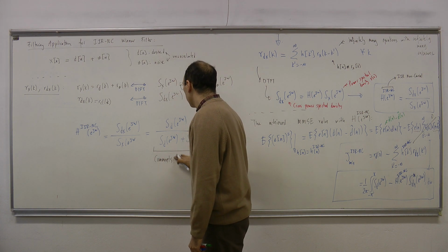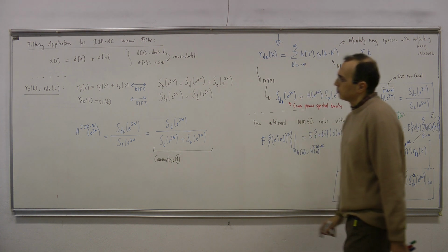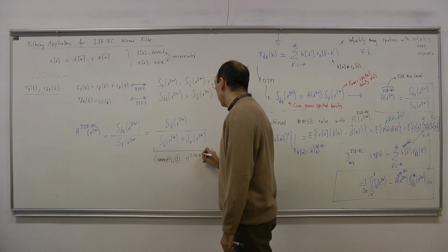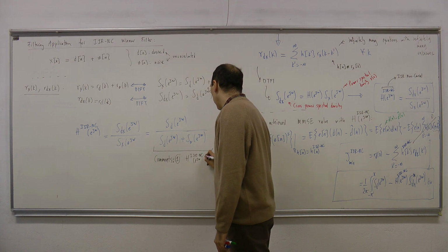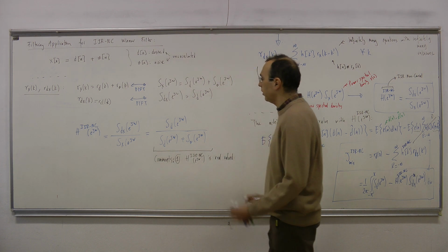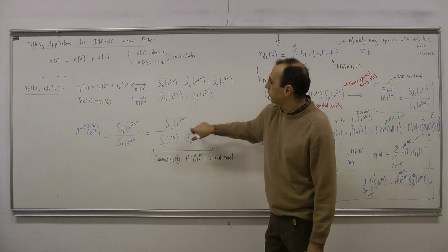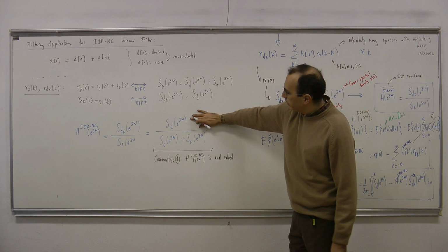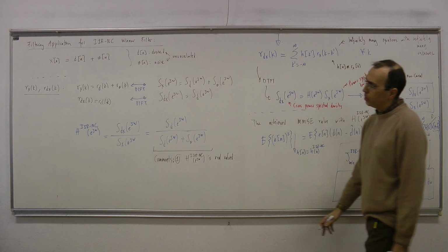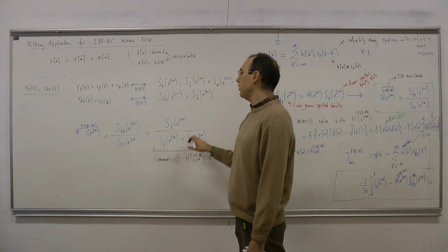So, I want to discuss the properties of this filter. Number one. So clearly, this IIR non-causal H(e^jω) is real valued. What do I mean by this? Well, the numerator is real valued. Furthermore, this power spectral density is positive, non-negative, I should say. Okay, non-negative, and this is a real quantity. This is also the same. So the ratio is also a real valued number. So for every frequency, I have a real valued number like that.